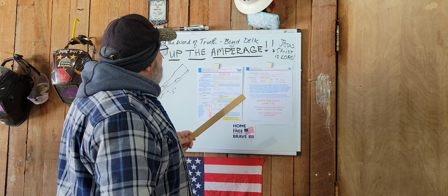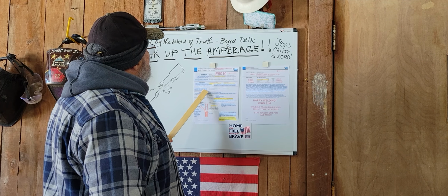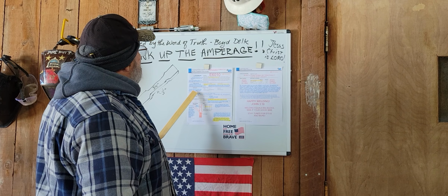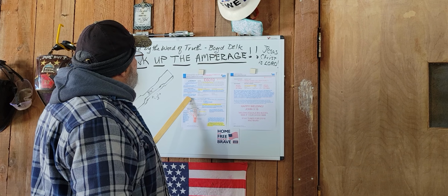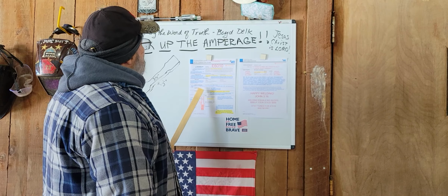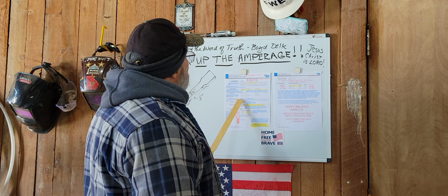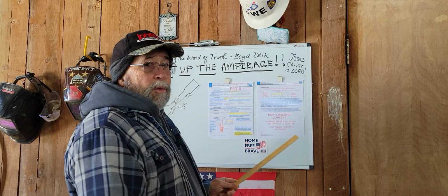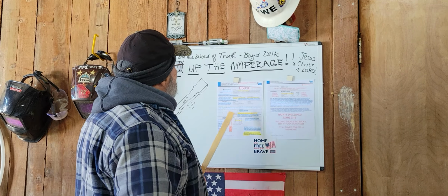I talked about cellulose. The coil wire of an E6010 electrode is made of mild steel. Mild steel is a low carbon steel which is more ductile or bendable, malleable or shapeable, and weldable. So the mode of welding with the E6010 electrode is DC current, or direct current, in which the electrode holder is hooked to the positive side and the ground is to the negative side.